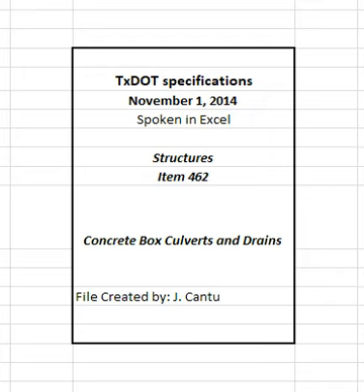Use Class S concrete for top slabs of cast-in-place concrete culverts for culverts with overlay, a 1 to 2 course surface treatment or a top slab that is the final riding surface unless otherwise shown on the plans. Use Class C concrete for the rest of the culvert and for all other cast-in-place boxes. Culverts with fill do not require Class S concrete.